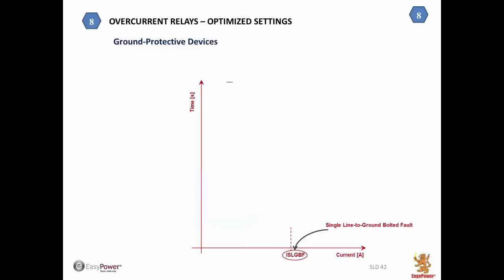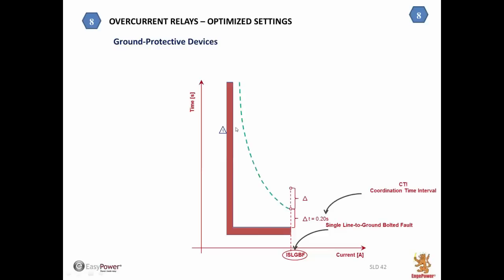For ground protection, we also normally have the ground setting of the circuit breaker. You also have the inverse time relay. It's the same situation. What we do is that if you have a single phase arcing fault here, it is very important. Another important thing is that IEEE 1584, when it says arcing, is always three-phase arcing. But here, in this case, I am talking about single-phase arcing. That's different from three-phase arcing. Okay?